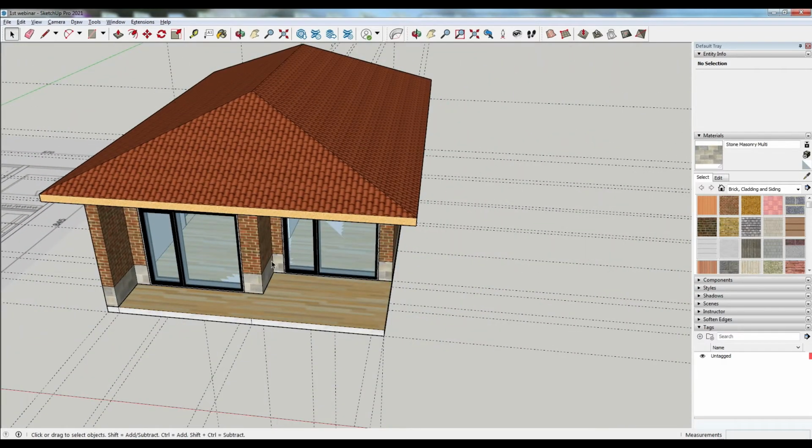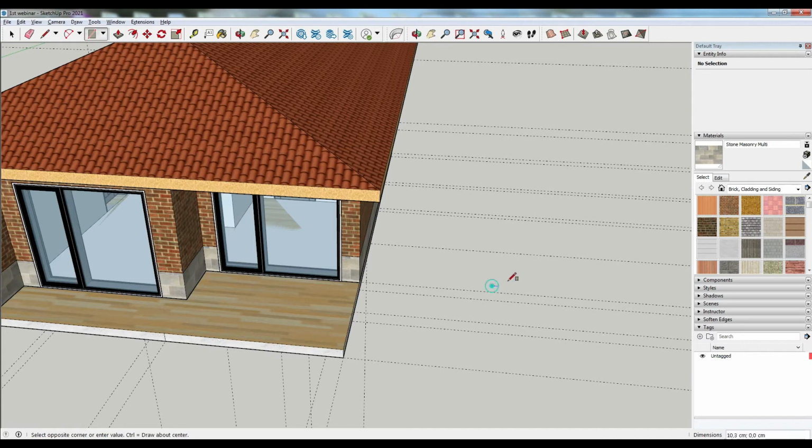That's why I will draw on the right of my model using rectangle, typing the sizes that I need, and then I will use the offset tool, giving a direction to the inside, and again I will choose the size. I will click with 3 clicks on the elements, and with right click I will make them one group.